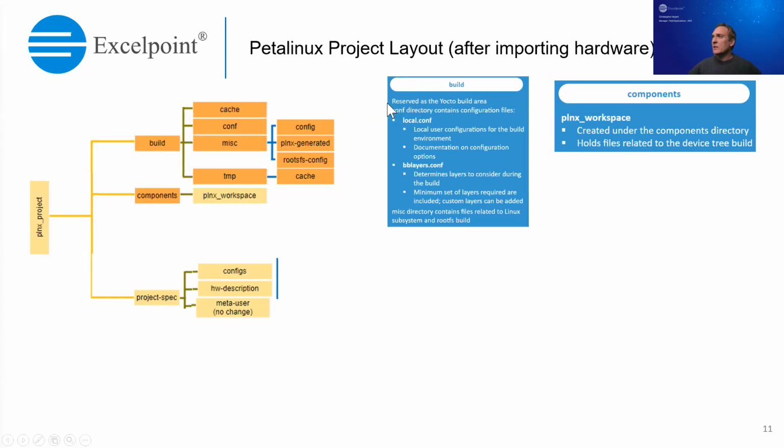Yeah, so the build directory is reserved as the Yocto build area. It contains also other subdirectories. And the files in this layer, though, should never be updated as they are generated by the Petalinux commands. So this is when you import the hardware. So there's some details.